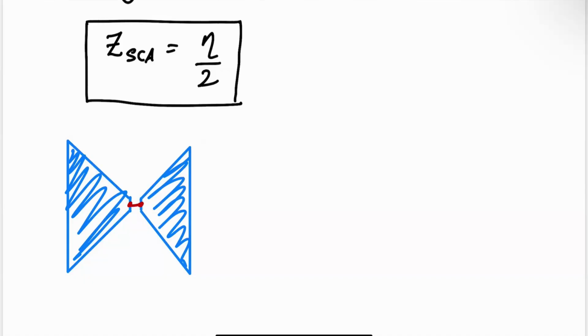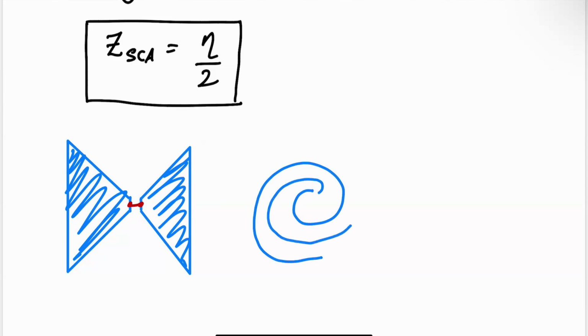Another set of antennas are spiral antennas. One port like that, the other port like that. So it doesn't look very self-complementary, but of course, if you add some thickness to this, then it becomes self-complementary, as long as the thickness and the gap are the same. And there are different kinds of spirals. There's the Archimedean spiral, there is the planar spiral, and so on and so forth. And they all are self-complementary.